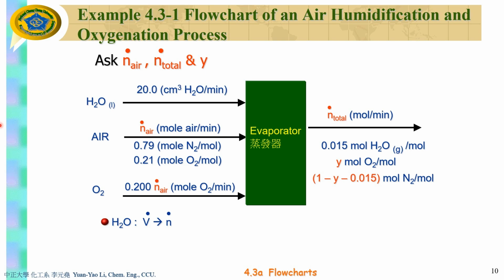By the way, the important thing is this is 20 cubic centimeters. It's not mass. Input equal to output always represents mass only, or energy or momentum. It doesn't represent volume input equal to volume output. No. So you have to convert this volume to become mass, or become moles, right? Because you have moles in, moles out. The conversion factor from volume to mass will be density.